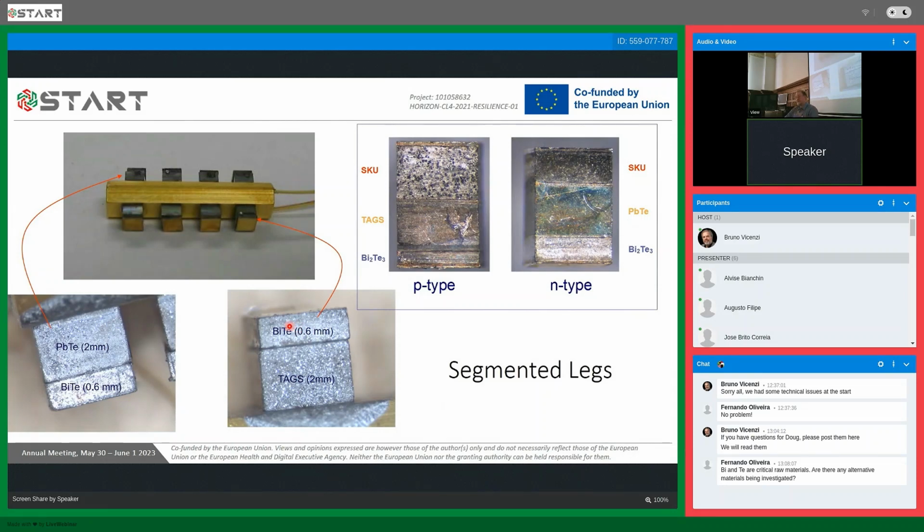But it can only really be used effectively to maybe 300 degrees Celsius. Certainly not to 400, that's where it starts to decompose, but I have used it up to about 300 C. It's really most effective colder than that, and so that is an issue with bismuth telluride.